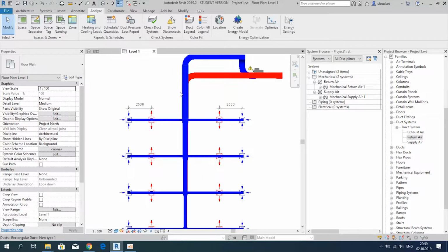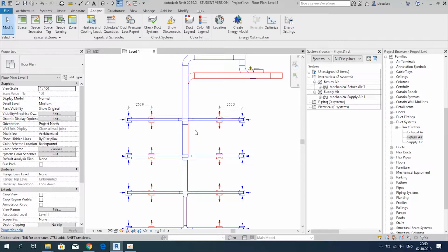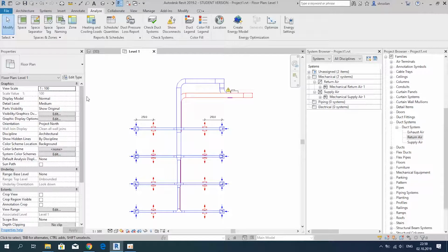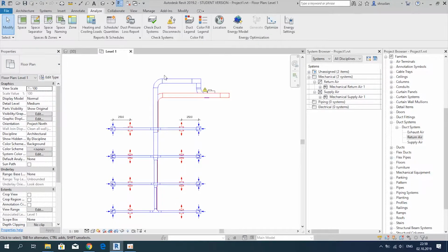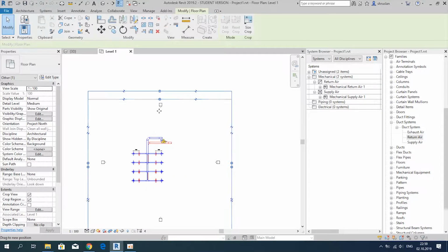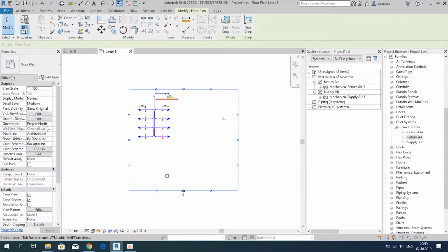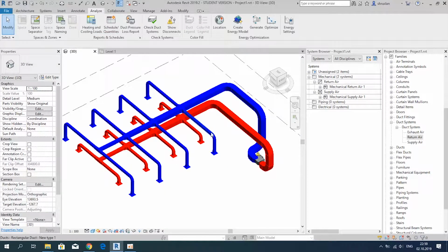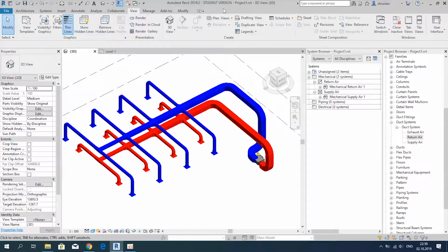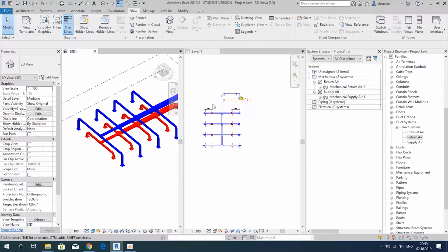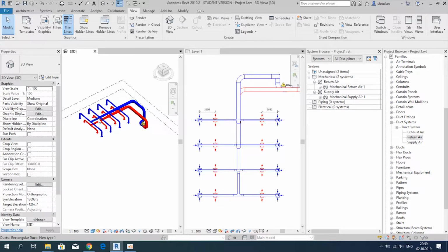Go to the floor view and limit the plane with the help of the view frame. For this, we should click on this little button under the workplace and move the frame on the left and other sides, all around. Okay. And if we want to see the 3D view and plane in the work window, we should open only these views and click on Tile Views in the View tab. Okay, we can work in these views at the same time.